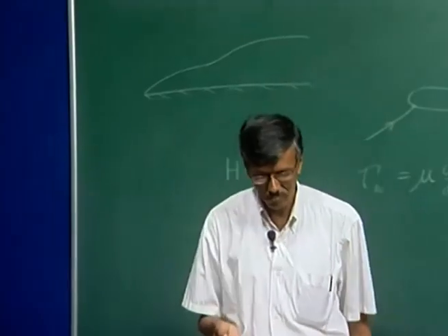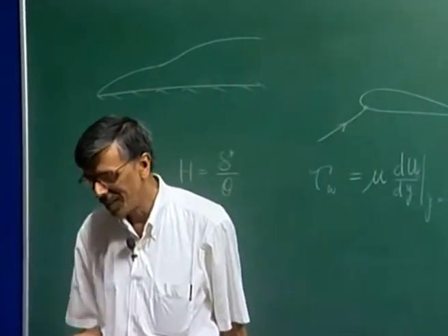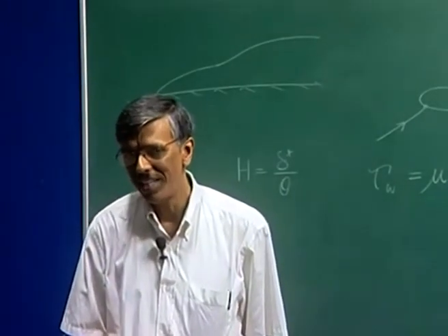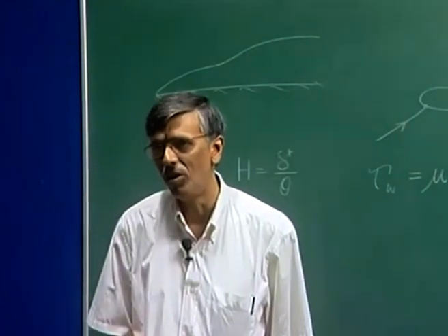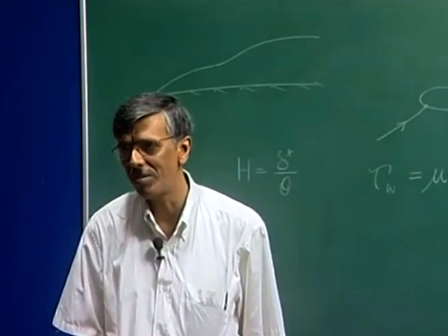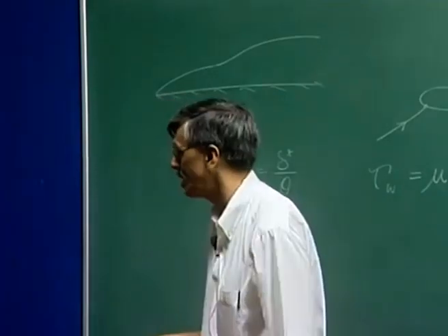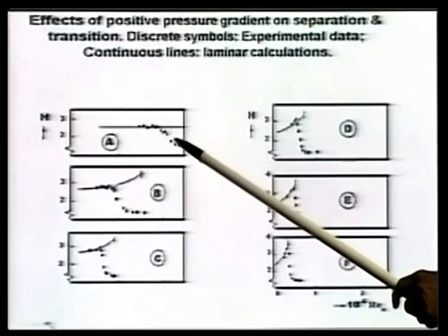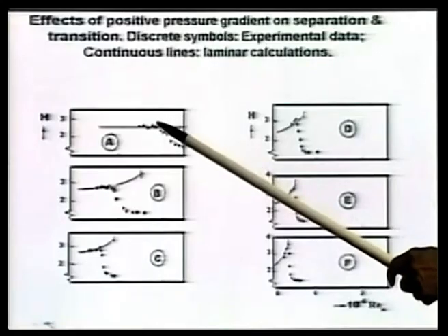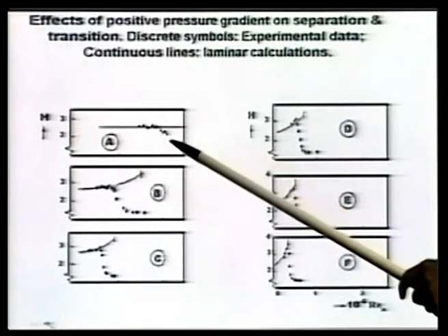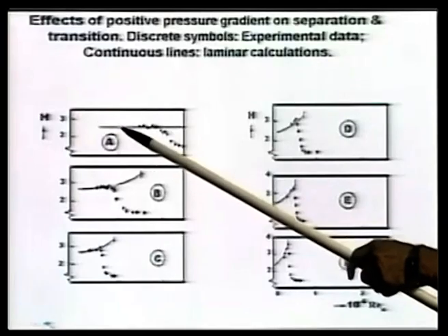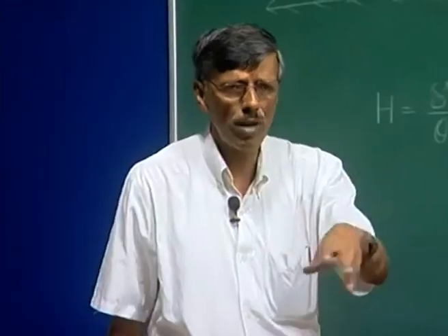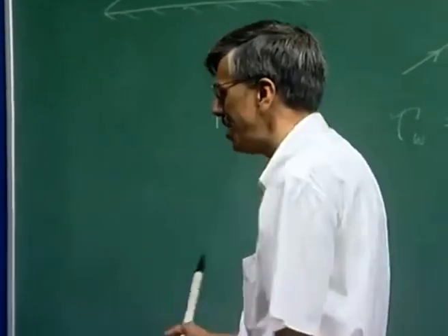So, we are talking about a physical understanding of features of the mean flow, the equilibrium flow, that helps us identify what is going on in the flow. We do not need to really do those detailed stability calculations to even comment upon things, but if I do plot, let us say experimentally, H versus Re, and if I see that this is falling off, this indicates there is a sort of a gradual transition that has taken place. So, the value of H has fallen from 2.59 to somewhere between 1.3 and 1.5, right.